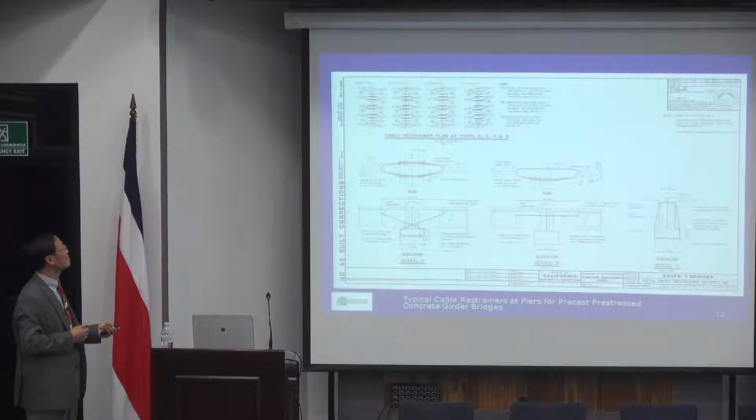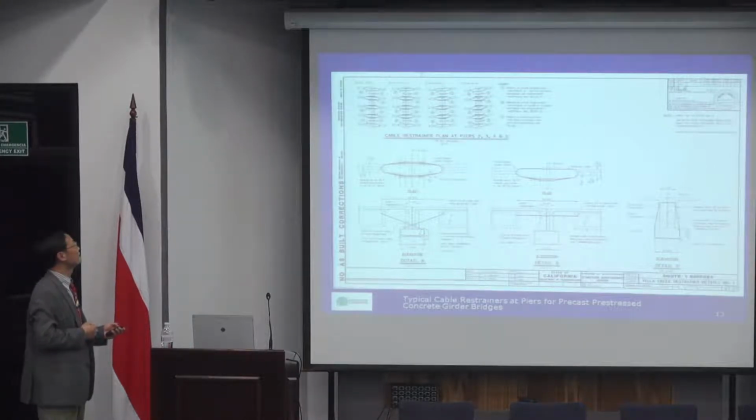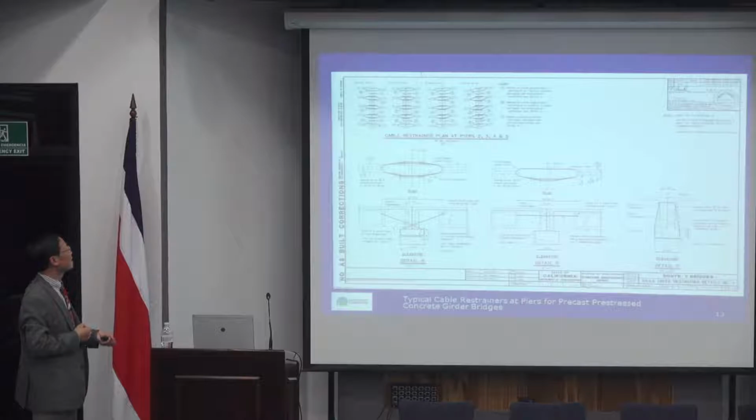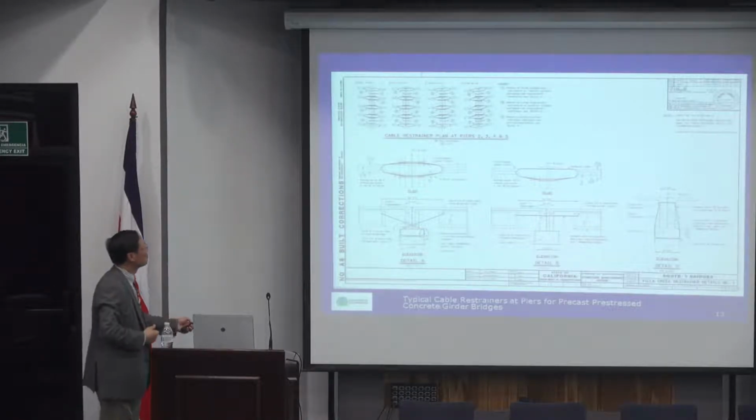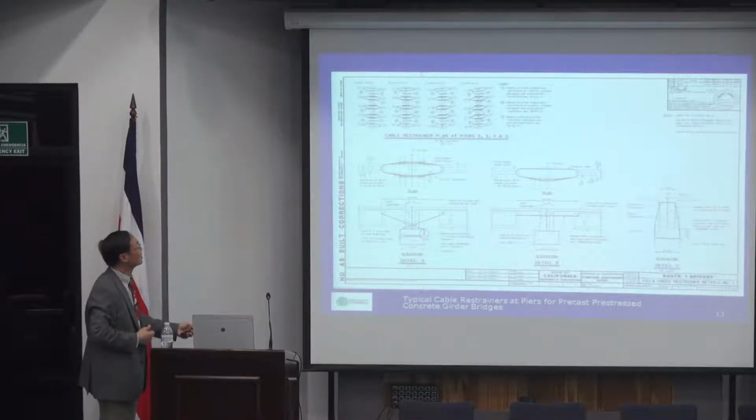And this is another bridge which is very similar. That's a concrete bridge. If you have this kind of situation, you can use cable. Basically, just have cable to connect from that pier all the way to that, and that. Usually, if you have a roundup, you can tie that easily. You can stress that. If you simply connect these two points, you can prevent longitudinal movement.